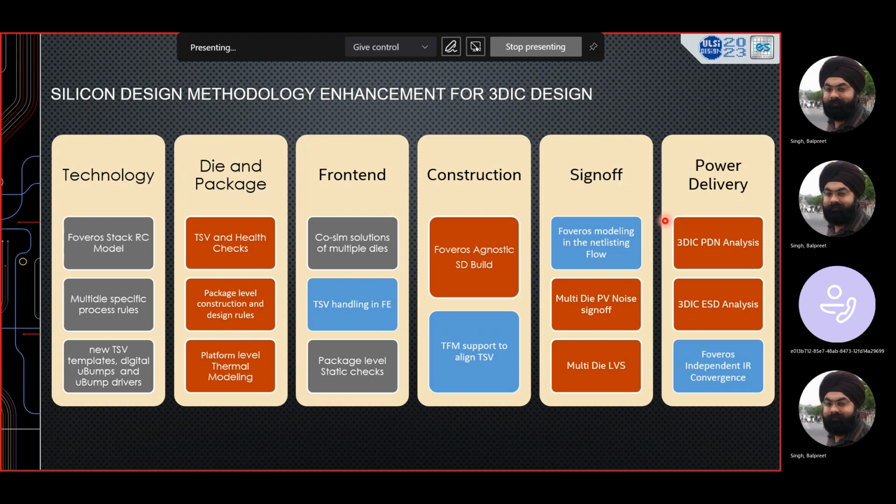And you need to also ask them, think about this: when you try to sandwich these two dies, by default, the microbump pitch is common. That has to be common, right? So both the processes you choose must be supporting this common bump pitch. That's why it is important to have this aligned with what you want to take out. Maybe tomorrow there will be a consortium where it will be standardized, but today it is not fully.